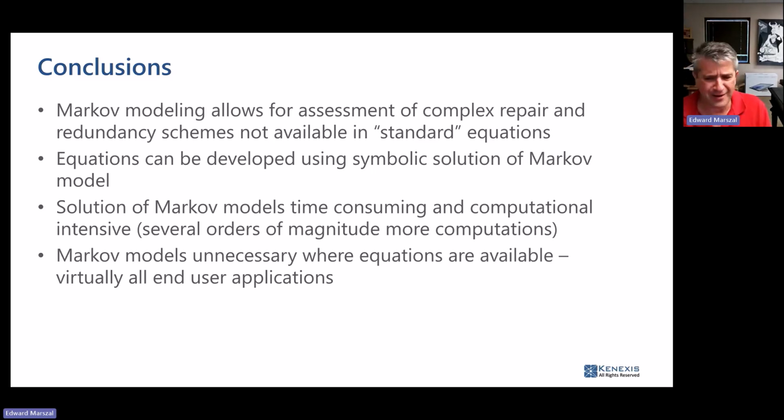And in reality, if you wanted to model that, then you should be using your site's failure rate data instead of trying to use some sort of hocus pocus to model a predictive FMEA and map that to how that FMEA number would change based on the quality of the maintenance that's occurring at the plant. So that kind of site index is actually modifying failure rates. It's not adding or changing states in the Markov model.